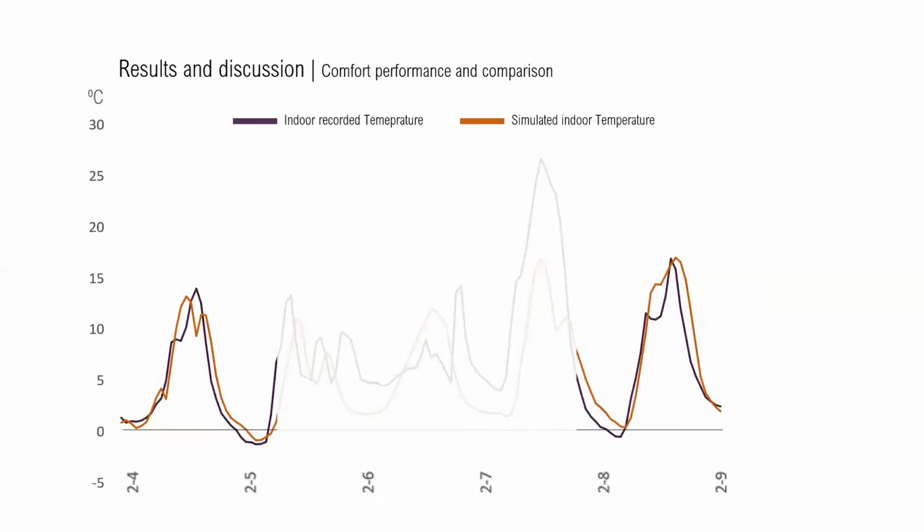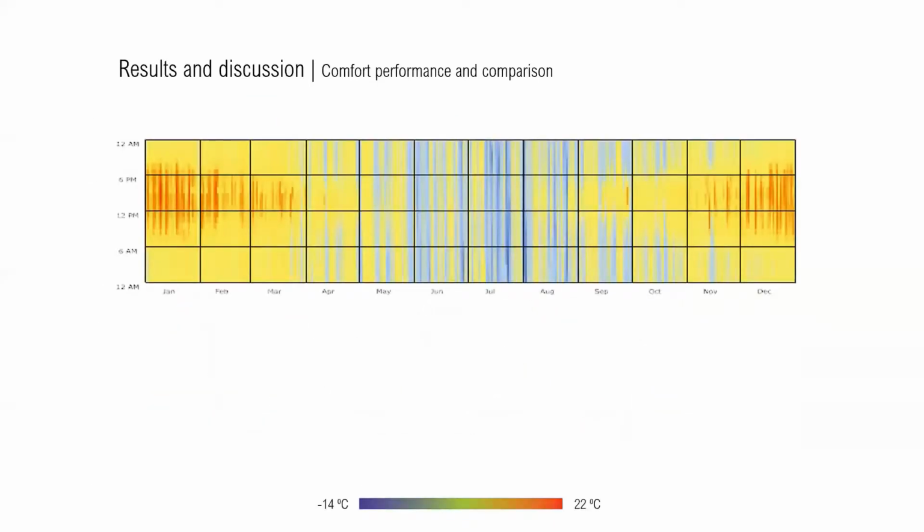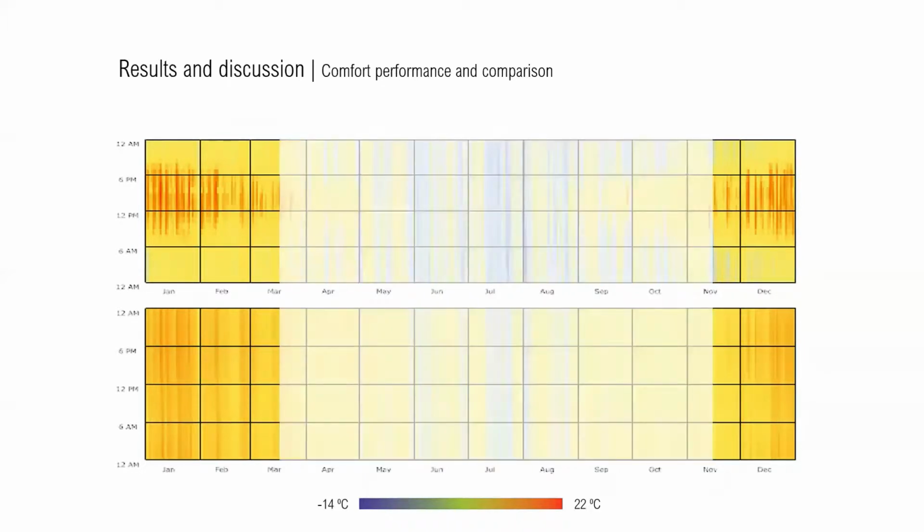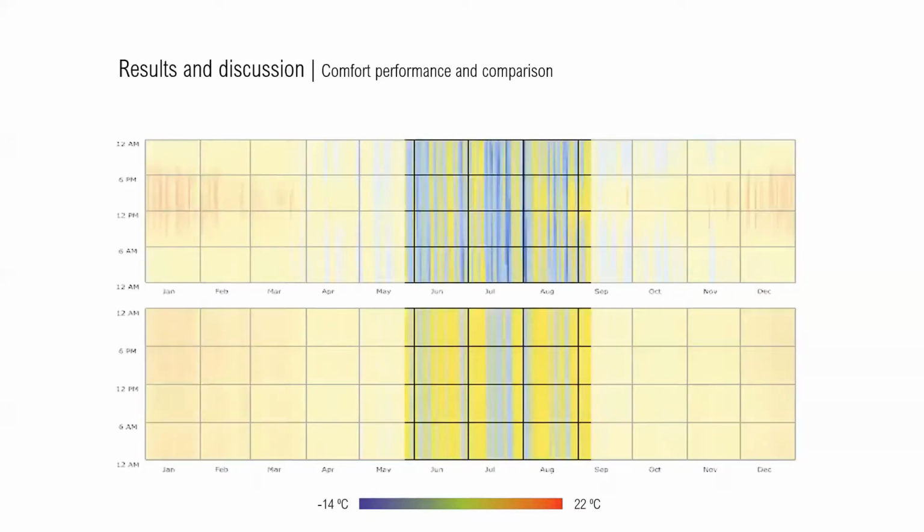When comparing the shelter's simulated annual indoor temperatures with that of a permanent structure with standard-grade materials, the latter shows less thermal amplitude. From the heat map presented, during summer, the shelter's temperature reaches averages of 4 degrees during the night and 14 degrees during the afternoon. However, during hard winter, it shows an inability to sustain human life without extra support, with temperatures reaching -14 degrees.